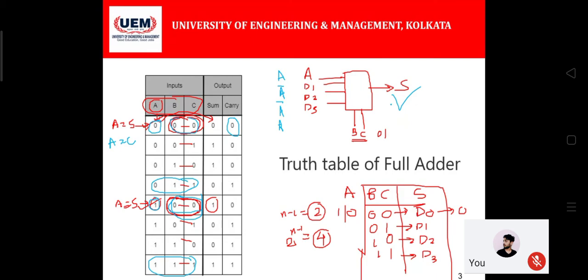So we do those programmings by incorporating millions of multiplexers within the device itself. Instead of dedicatedly placing a full adder, manufacturers provide two multiplexers there so that those multiplexers can be programmed to behave like a full adder when required.